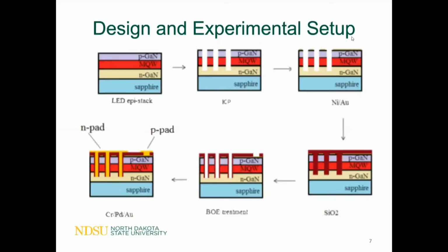The steps for fabrication of the gallium nitride-based LEDs are shown in these figures. First, the LED must have a mesa structure, which is used to avoid a sharp curvature of the positive P region next to the N layer, and periodic microvia holes made by ICP etching, or inductively coupled plasma, which is a plasma source where energy is supplied by electric currents produced by electromagnetic induction.